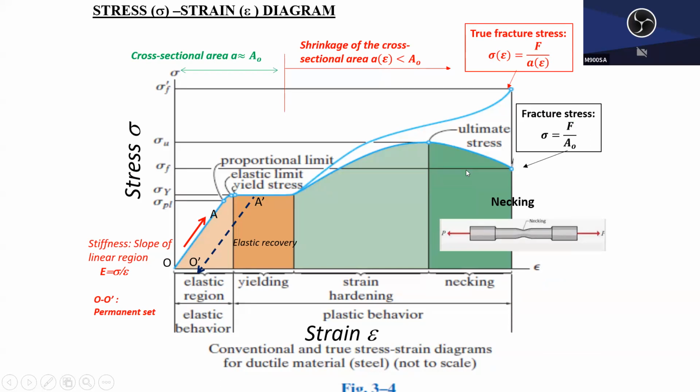If you pull the rubber, this linear part is very small, and after that is the long non-linear curve all the way to 100%, 200%. Most of us think this will never happen to elastic rubber. Actually, it does. At the very beginning, it shows something like this, but after that, we will have a long non-linear curve for polymer or rubber.